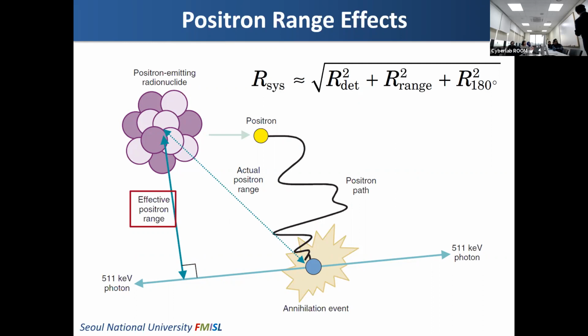With longer axial length, the sensitivity will be higher. Or if you have a smaller diameter with the same axial length, you will also have better sensitivity. So a small diameter is better for higher sensitivity. This geometry factor is the main factor that determines sensitivity.